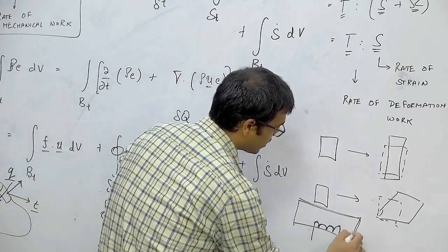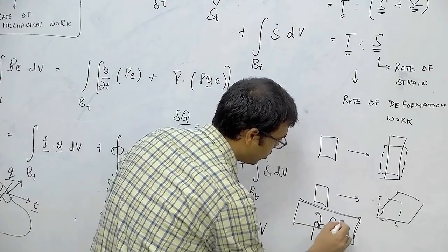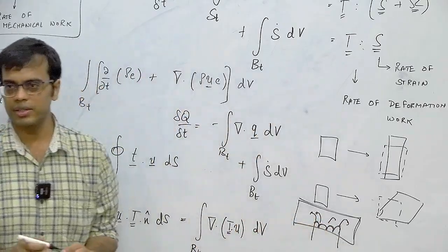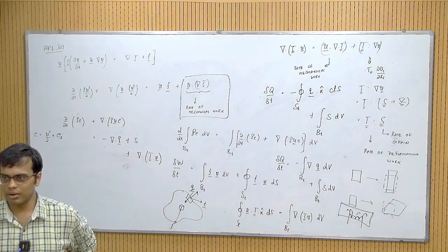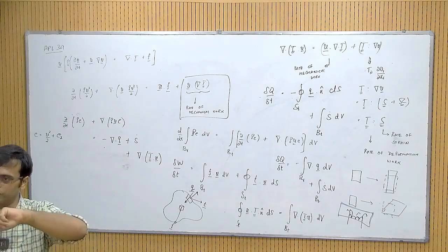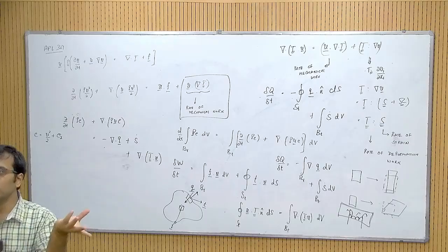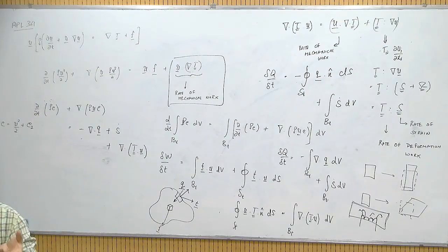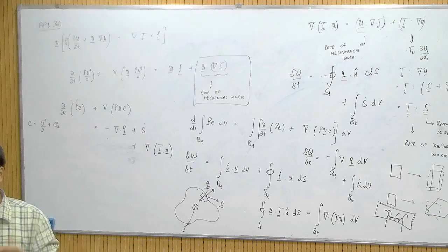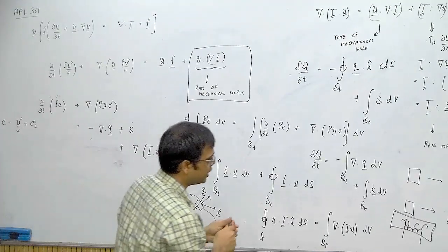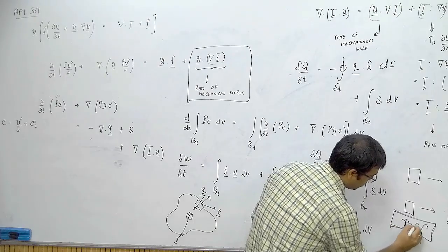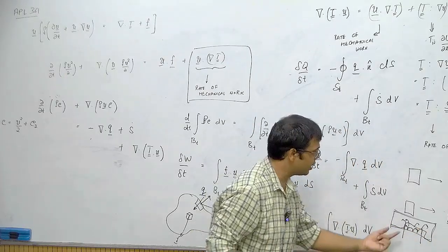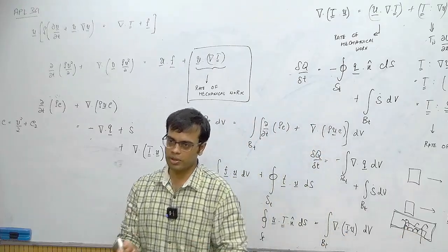If you are not interested in how the flow is going to convect due to the heating of the filament, then you could model it simply as a source term, part of the system, calling it S dot. Okay, but if you are interested in the details of how the flow is going to convect as a result of the non-uniformity of temperature of the air or whatever fluid is there, then you cannot model it as volumetric heating. You will have to solve for fluid flow in the domain where fluid is, and wherever fluid is not, that is the surface of that domain, right?